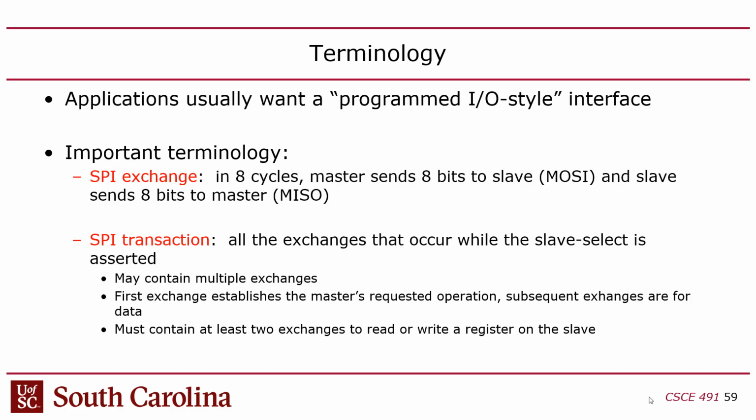But the actual transactional level protocol is defined entirely by the application. So what does that mean? Well, again, you got to look at the data sheet of your peripheral to figure out what transaction level protocol it's using, because it's not defined by the SPI standard. And then you have to write a driver for your microcontroller that basically hacks SPI to achieve that protocol.